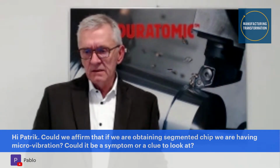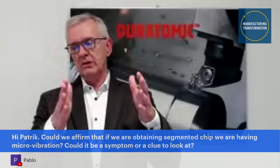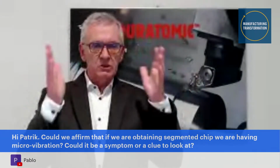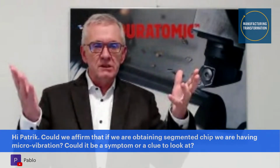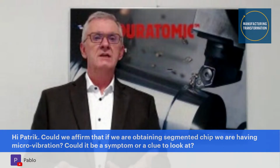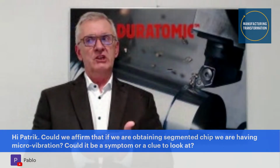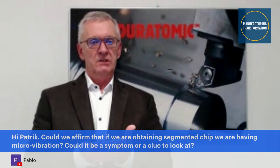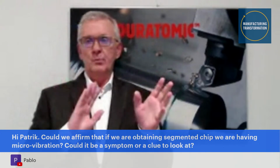And then together with that question is, could that be a symptom or a clue to look at? Yeah, of course. I always tell people, look at cutting edges, used cutting edges, look at chips. They tell you so much if you listen, if you watch. A segmented chip should for you say, double check on micro vibrations. And if nothing is going on, okay, perfect, but there is a risk.